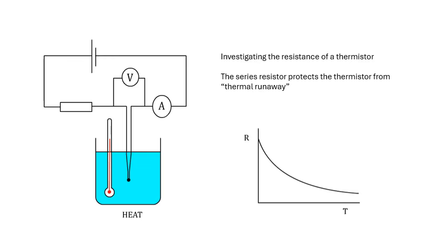And I've had to deal with many a molten thermistor in my time. Yeah, you should always have a resistor in series with it to protect it. Yes, if it comes up in an exam, to protect the device. That will do. That would get the mark.